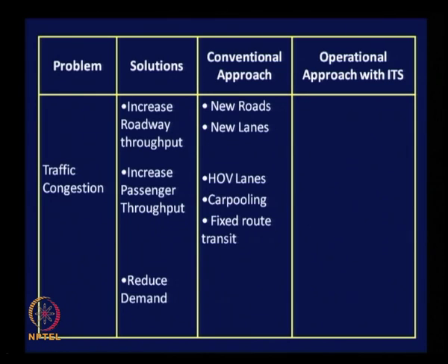And another possibility of reducing congestion is by reducing demand itself over space as well as time. You may wonder whether it is possible to reduce demand. It is not desirable also to reduce demand. We must encourage mobility in general, because mobility is a key for growth of socio-economic activities. So, our transportation planning process should not end up with curbing mobility. Here what is meant is to spread out the demand over time as well as space by some appropriate means.